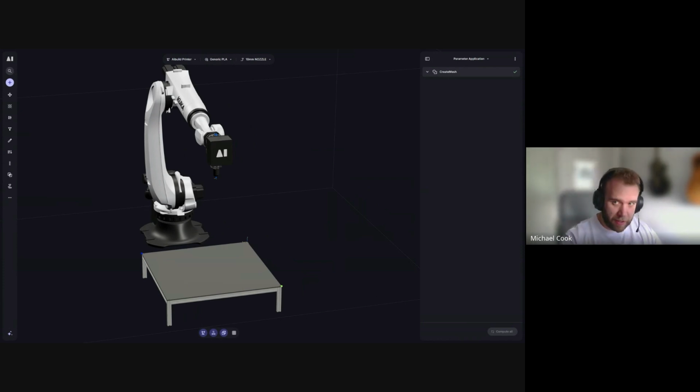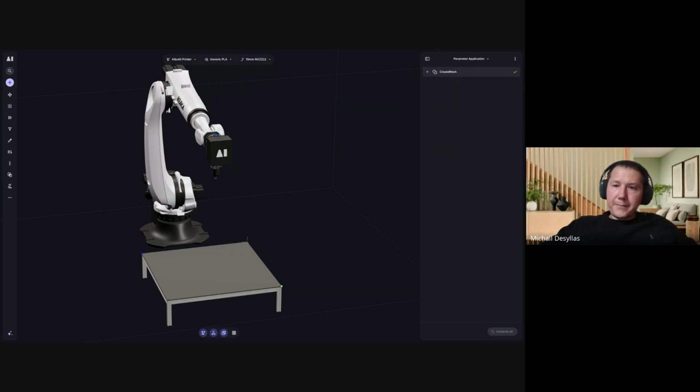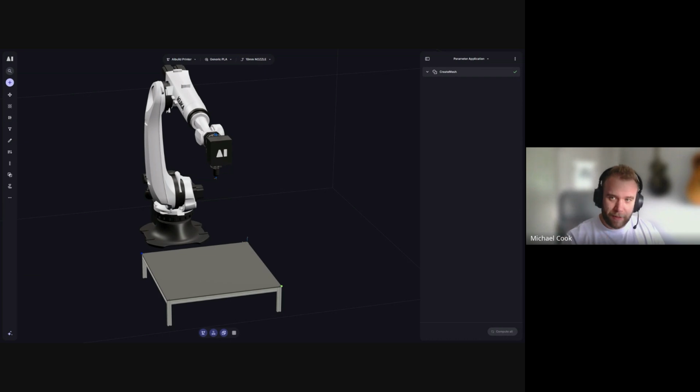So you access the printer settings, go to your post processor setting, select custom, hit the setting icon, and then you'll find that when you scroll down through the information within that dialog box, you'll see process parameters, and there's a checkbox. Tick the checkbox, press save again when you exit the custom post processor, and then that will bring you to this screen and the ability to use the edit operator and the process parameters.